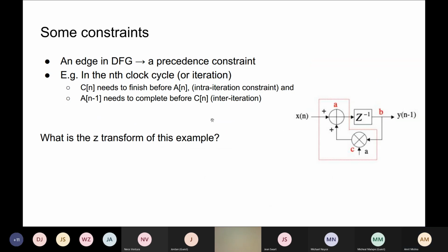Now, this is a simple block diagram again, but this time we have a block diagram with a feedback. So it's actually an IIR filter. And of course, you can try to see if we can draw the Z transform of this operation, because as I was saying, it's easy to write down the Z transformation of an operation just by looking at the block diagram.